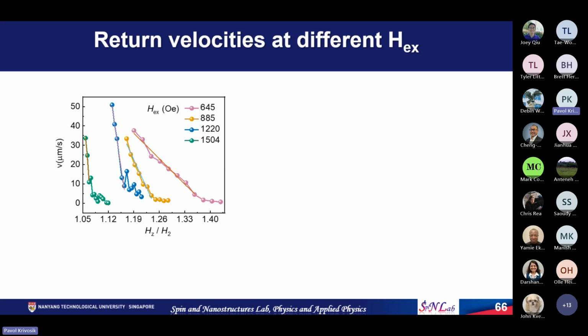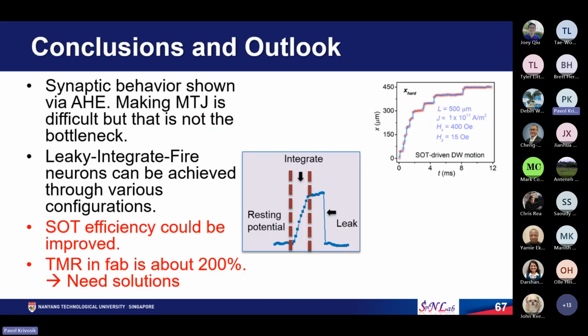Okay. So the conclusion is that domain wall based neuromorphic computing is more practical. The materials that we use for these demonstrations are already used by the MRAM industry, so it's already CMOS friendly and can be manufactured easily. Secondly, we are making neurons and synapses with only a small tweak. Using the same material, you do the lithography to have a pine tree structure for synapses, and make a straight wire for neurons. Just by changing the lithography steps, you can achieve both synapses and neurons with the same circuit. That is the beauty of this particular concept.